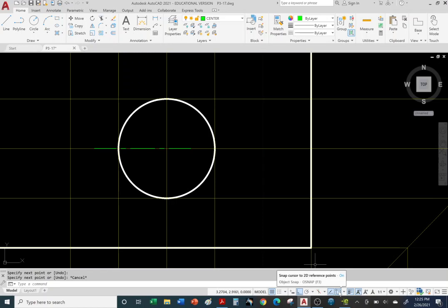So let me turn off Object Snap so I can have freedom to extend. Make sure you have ortho on, right? So to guarantee we stay horizontal. Okay, and there it is. And hit escape. All right, and just eyeball it. Now let's do the vertical.